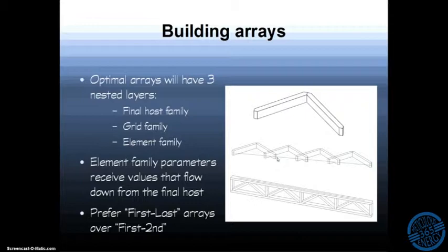The most common middle family is a line-based family, which is what I'm showing here. And it can stretch in length with easily controlled end conditions, but you can sometimes have a waffle pattern or any other type of sub-family that you're going to load in, but controlling the array into a simplified family or controlling the element into a simplified just array family and then putting that array places is the way to go.